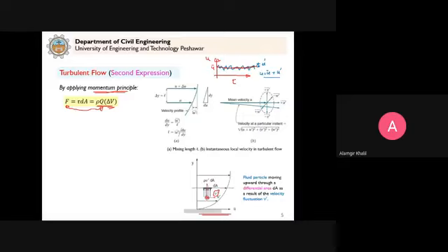Now because of this, there will be a flow of the fluid across this line here. So if we consider this line here, we consider an area dA. Now what will be the flow? That discharge we need to calculate in this equation. Clear? So in that case, this discharge will be v dash times dA, because this is the velocity and it is occurring through this area dA.